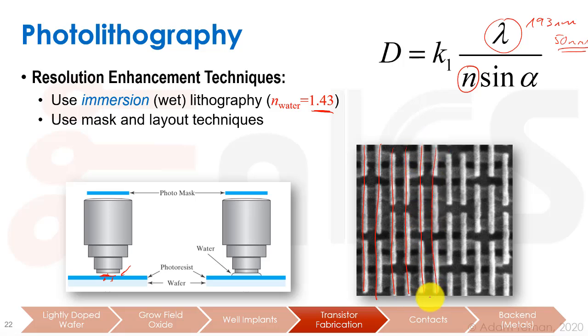In fact, this is something called double etching. So what we do is we use the optical features of making these things. We can tune it to cover the whole wafer basically with these straight lines, and then on a separate process step we can go and just etch away the areas we want to break. This is a much lower resolution, so it's a much larger distance and it's easier to etch these things away. So that's called a double etch, because we first etched away this stuff in the middle and then we etched away these parts over here.